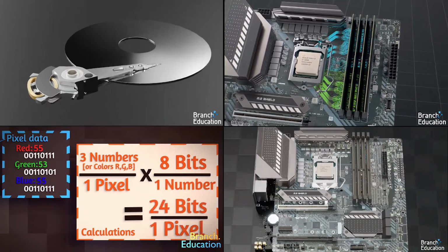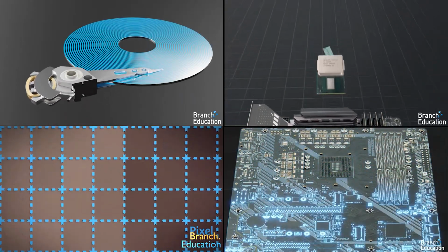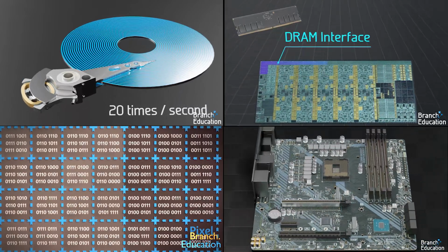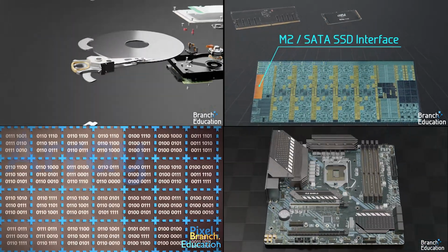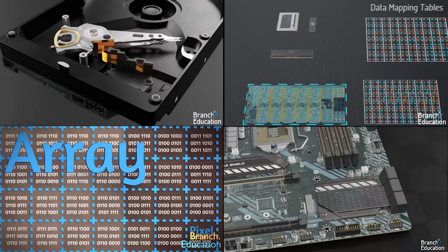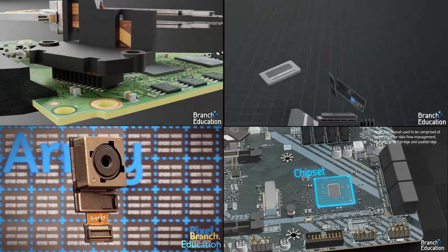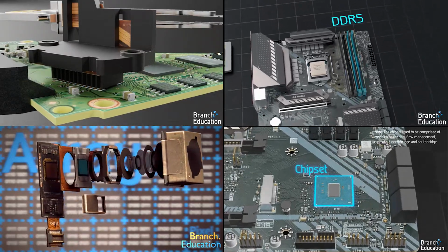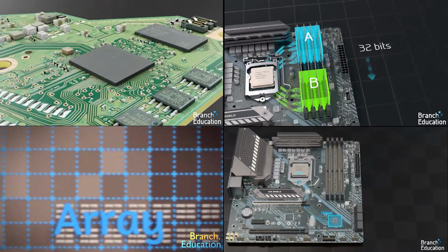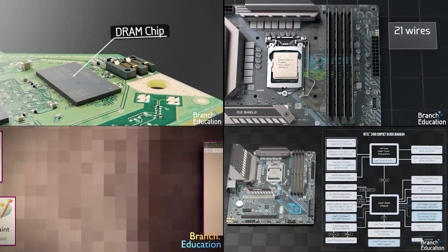This motherboard is a massive printed circuit board with thousands of wires running inside and a variety of microchips, components, sockets, ports, slots, headers, and connectors soldered to it. Perhaps the single most important and expensive component, aside from the bare PCB, is the chipset, which is this integrated circuit found underneath a heatsink down here, and is connected directly to the system agent section in the CPU. Here's a diagram illustrating how the CPU and chipset are connected to everything else.